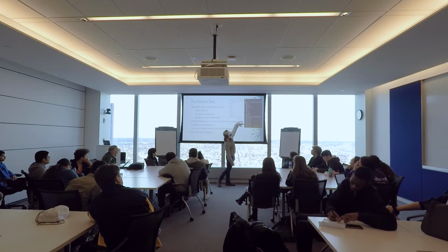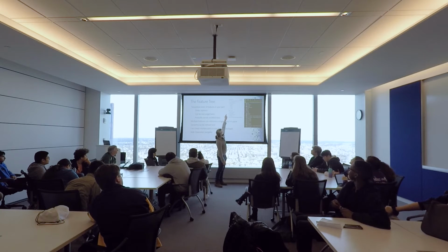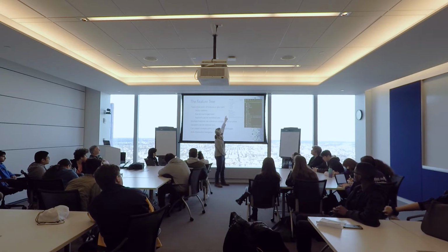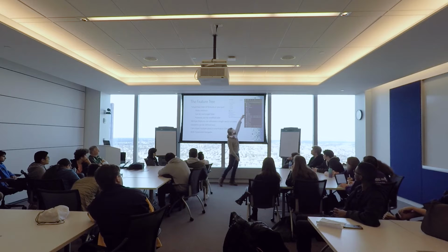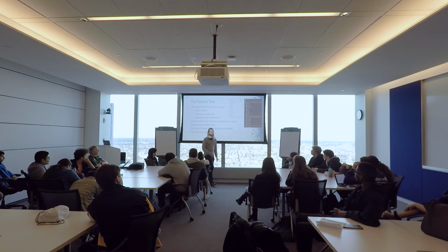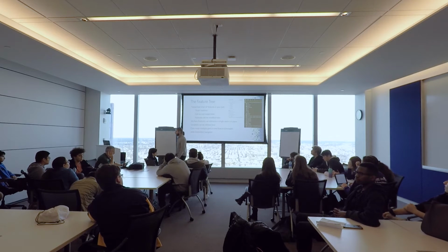SolidWorks has a few extra things at the top, but they start with the origin and the planes, then sketches and then features as you go down, and each one of those is in order. For example, this 3D sketch was pretty much the first thing done in this part in SolidWorks, and that x-axis sketch was the first thing done in the Onshape part, and then the first revolve happened after that.